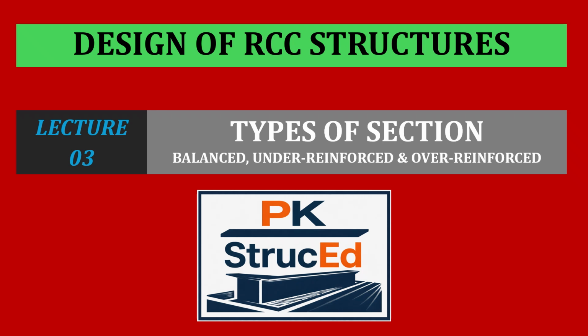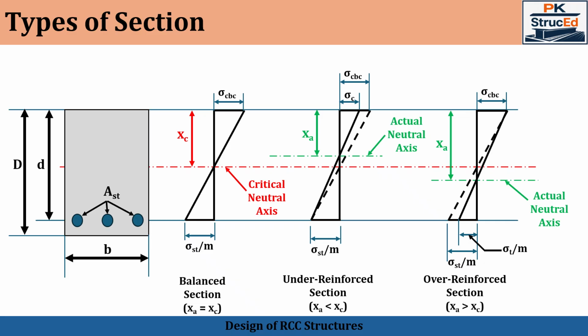Understanding the types of section is essential because it helps us to predict the mode of failure as well as to ensure ductile behavior. In addition, we can also design safe and economical RCC members. In RCC flexural members, both concrete and steel resist bending moments. Let us consider a rectangular reinforced concrete beam having a width B and an overall depth D.